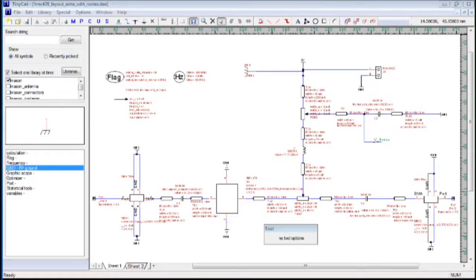I've gone another step beyond with this connector. The connector, I have a 5-terminal device. I've spoofed on the layout a 2nd terminal that's on the signal terminal, the signal pin, so that I can associate a simulation, a little bit of inductance, some parasitic inductance that's going to be modeled in for this connector.